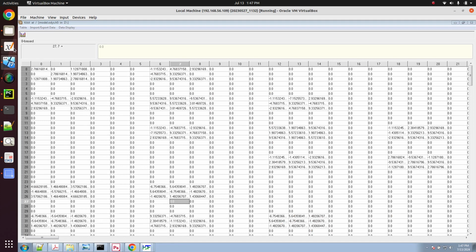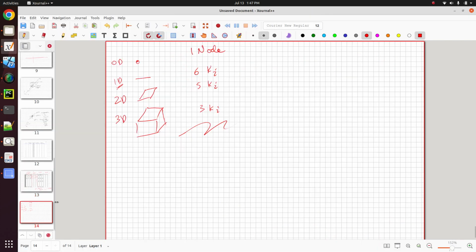And then it varies from element to element. So for 1D as an example, we get stiffnesses for all 6 degrees of freedom. So again, remember the Young's modulus, the length of the beam, the cross-section area, the moment of inertia. These are all values that contribute to the stiffnesses. Same thing for the 2D element.